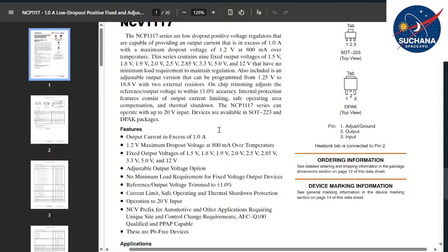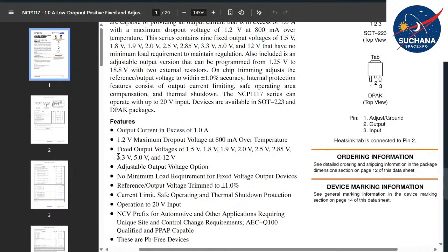That means 5 volt. But in the case of the Raspberry Pi 0 module, again you can find the NCP 1117 IC, but it is designed for an output voltage of 3.3 volt. Here you can see, this NCP 1117 IC is found.